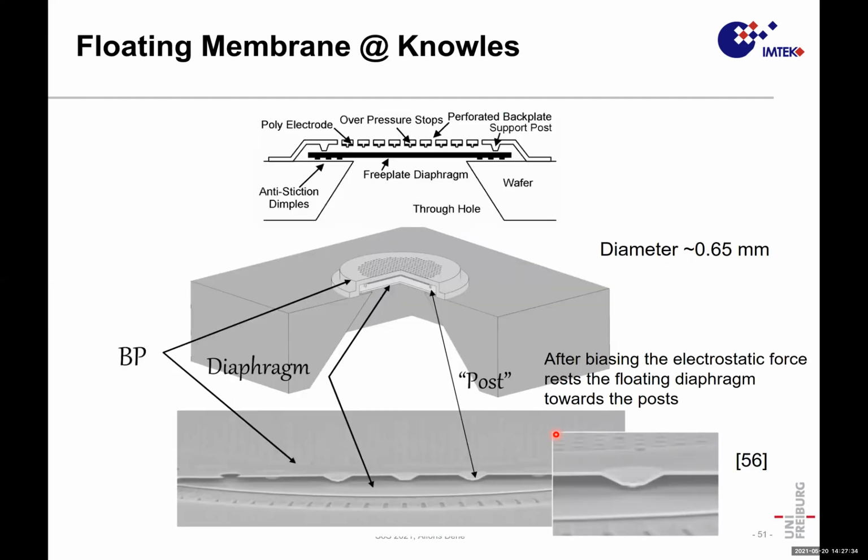Yes, and I also attach a floating membrane device example here from the company Knowles. Knowles, you remember, was the company that first did this microphone in the flip phone. And they invented very early this kind of floating diaphragm. If you see here the wafer, you have a piece of silicon diaphragm which is only 0.6 millimeter in diameter. As you remember, the smaller you can make it, the better if you have a floating device.